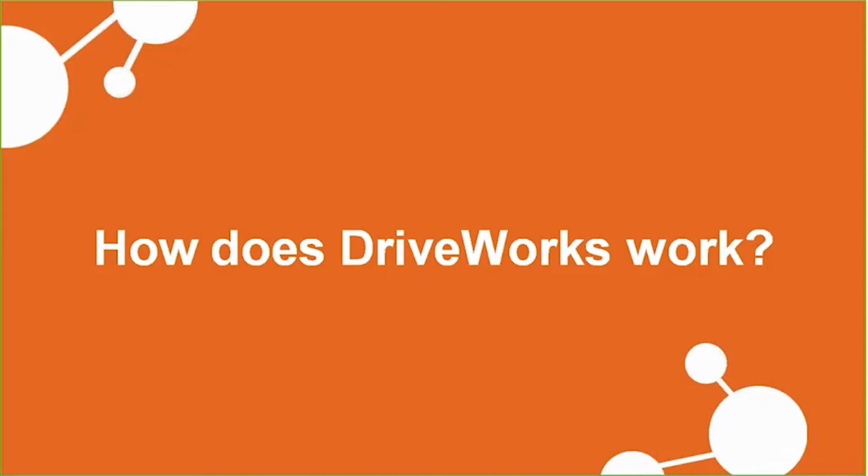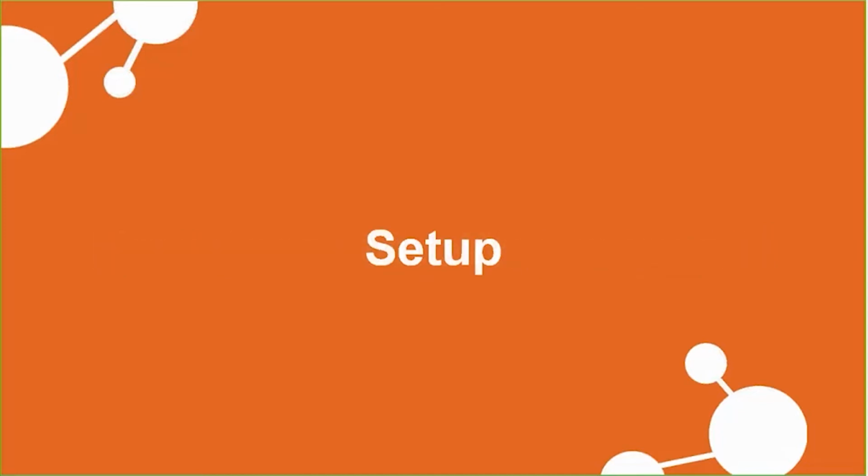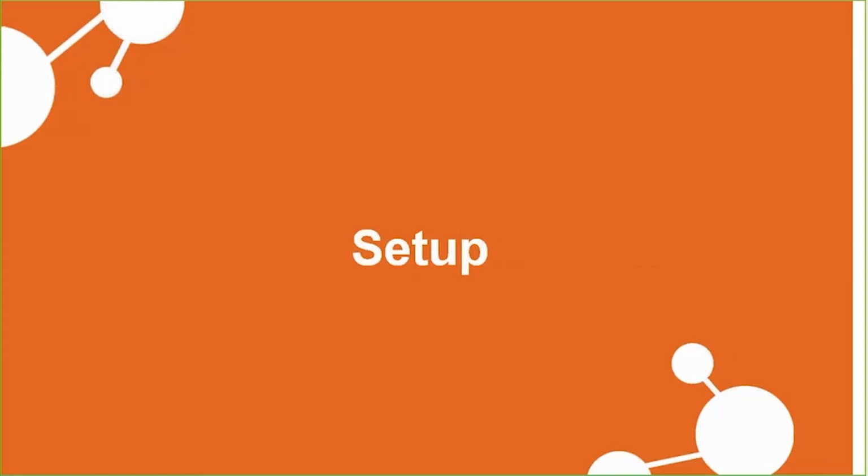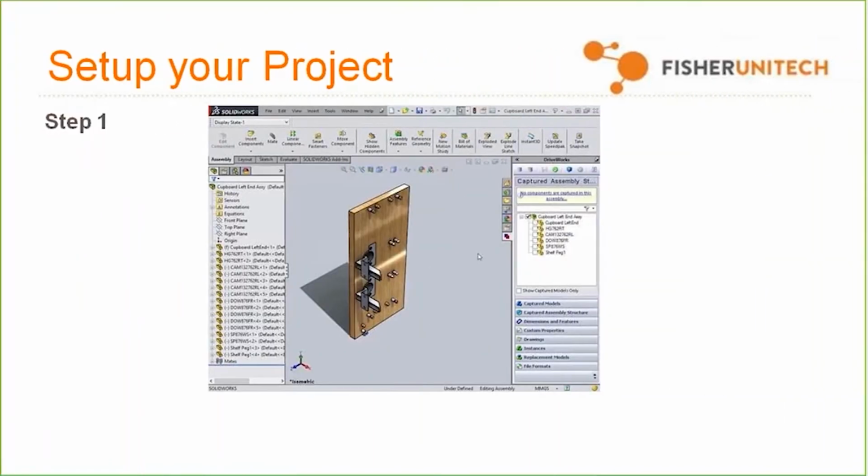All right, so how does DriveWorks work? Let's talk about the setup first. So what you see here is what DriveWorks looks like in a SolidWorks environment. So over here in this task pane, DriveWorks as an add-in is going to show up. And essentially what I like to explain when I'm teaching the software is that you've got to first pick out the assembly that you want to automate.